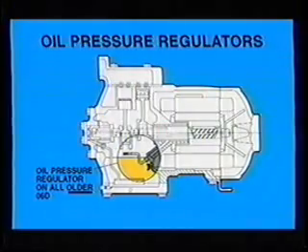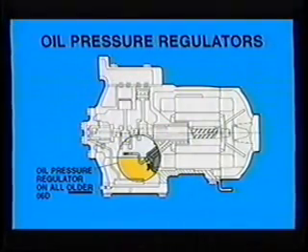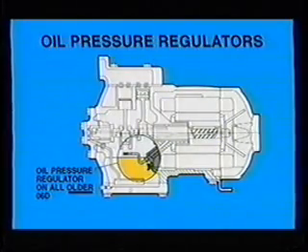An oil pressure regulator is used to keep the pressure constant throughout the system. The oil pressure regulator on all older O6D compressors was in line with the sight glass, so oil flow could be observed as it was sprayed from the regulator. On refrigeration systems where O6D compressors are connected in parallel, the sight glass opening is used for the oil equalization line. With the old type of regulator, oil could be pumped out of the compressor through the equalization line or float, causing a low oil level condition.